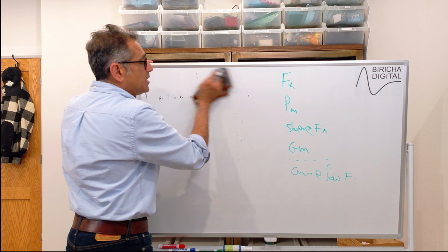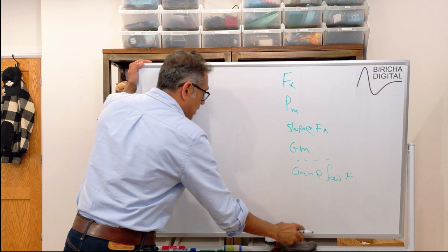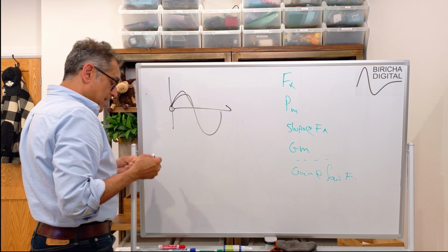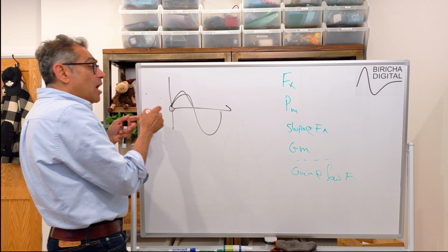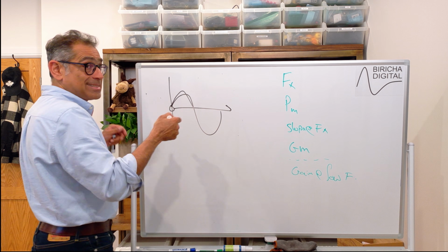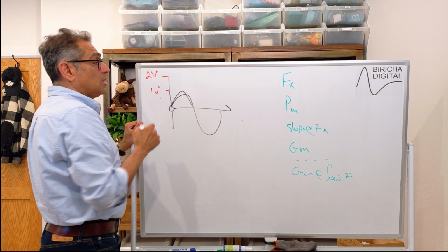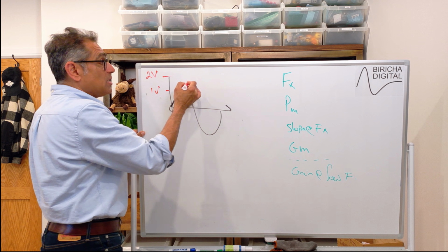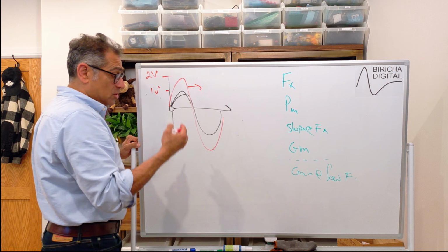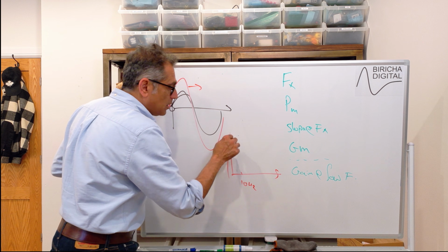So I have got a 10 hertz 1 volt sine wave. I am putting it into that network, and there you go, that's your 1 volt 10 hertz. Let us say that by the time it comes out, its height has doubled or halved, it doesn't matter. For simplicity, let us say that it has doubled. So I put in 1 volt and it comes out at 2 volts. Then my gain would be 2, because the one that has come out is 2 times the size that it's gone in. So I can go to my plot and I plot that at 10 hertz, my gain was